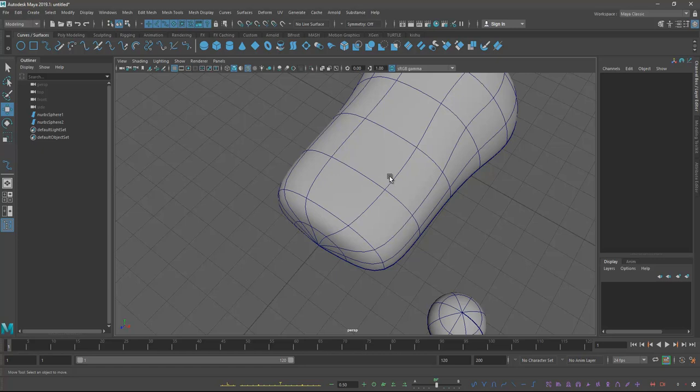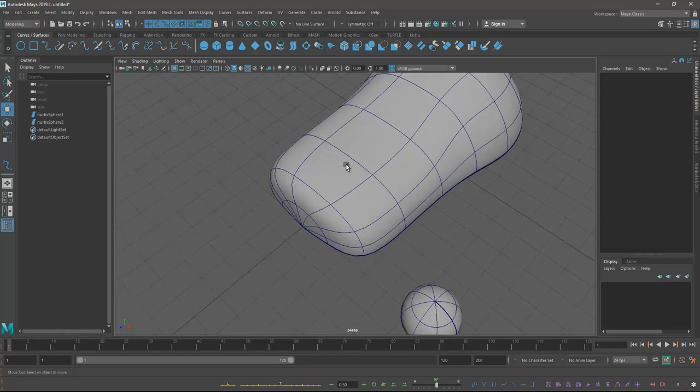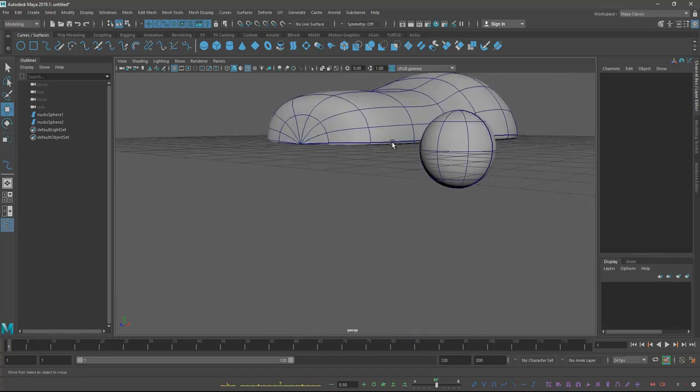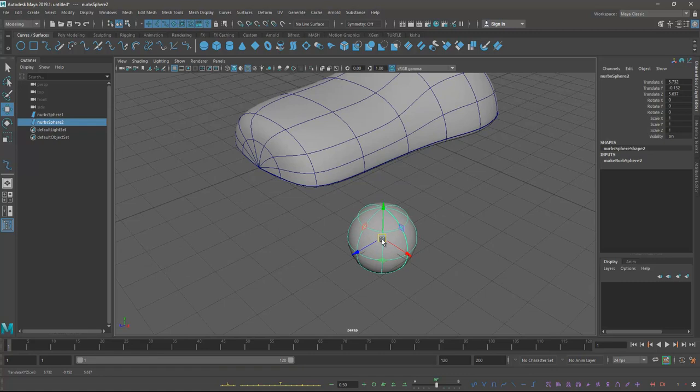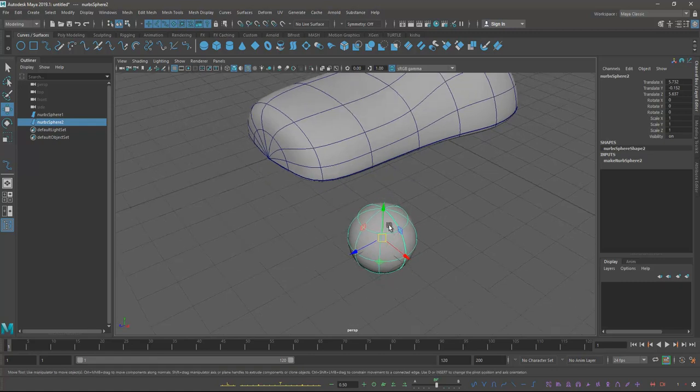When we generate the curves, the curves break into two parts if the seam line is disturbed. So make sure the seam line is on the side or bottom. Okay, fine. I will also show you after some time what the problem is when we use the projection method over the seam line.